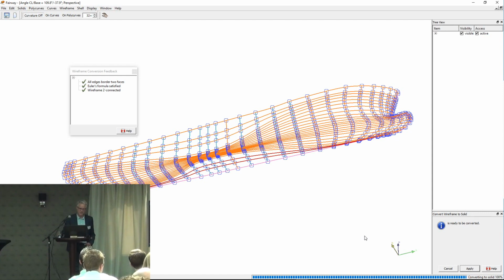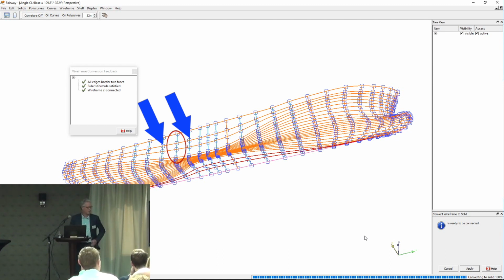Because any route from one point that would come back to make a contour on the shell could in theory be a shell part of the hull. Only you cannot come from this point to there without crossing this frame here. So we need to figure out the smallest loops in the model to figure out what is part of the shell plating and what is not.